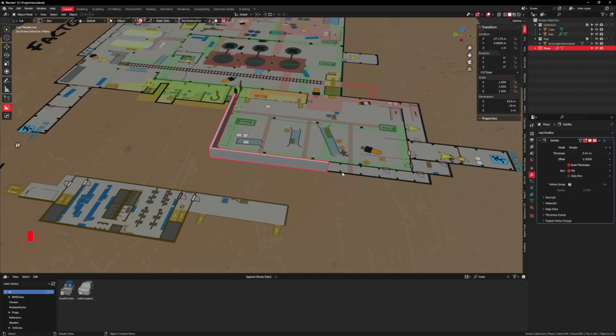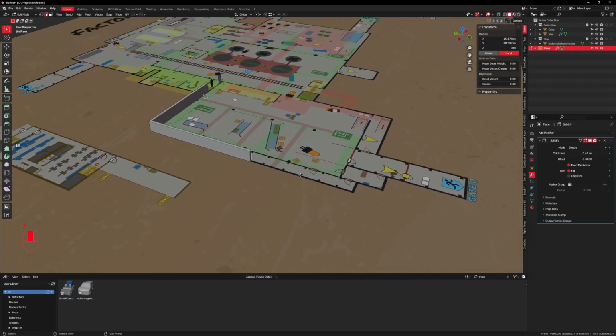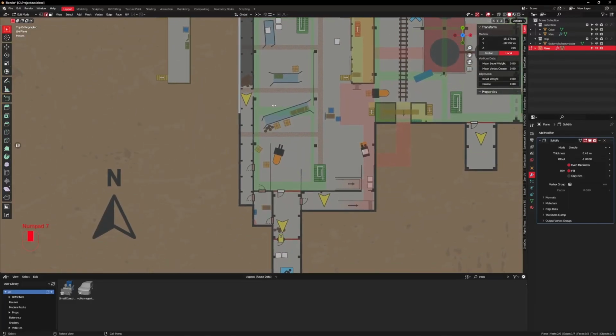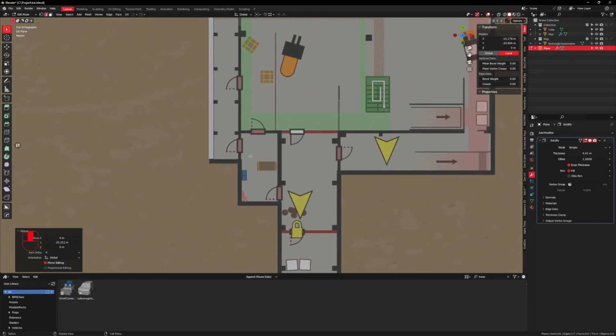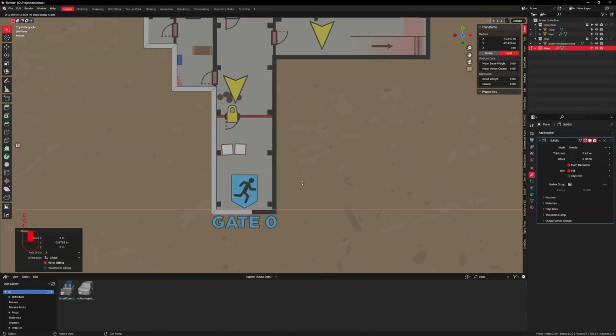Okay, go back into edit mode, edge select, click that edge. Let's go into top-down view and use G to move, middle mouse to lock on, and click. And then for every corner, I'm just going to E to extrude, middle mouse to lock, and then click. And then just keep doing that, E to extrude, middle mouse, and click. All the way around this outer wall.